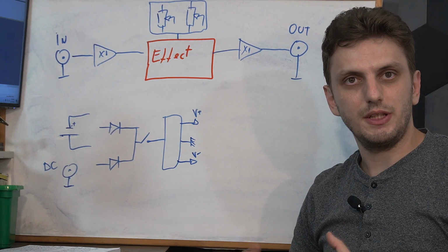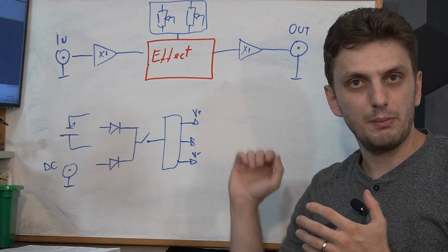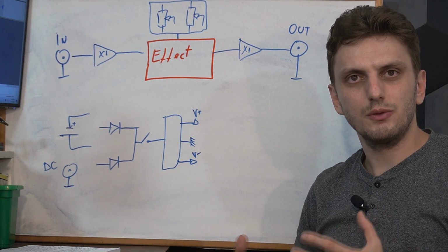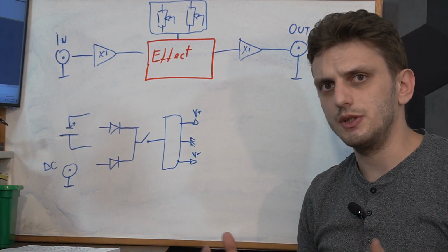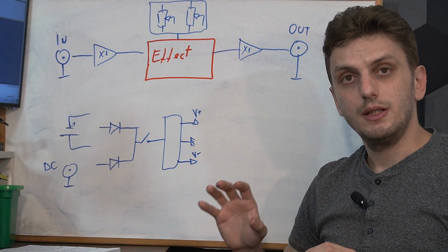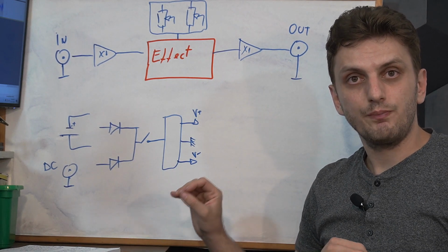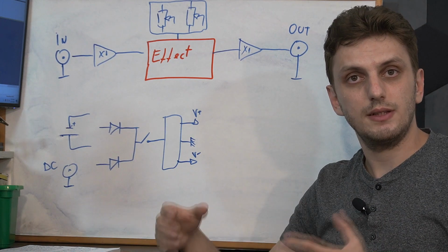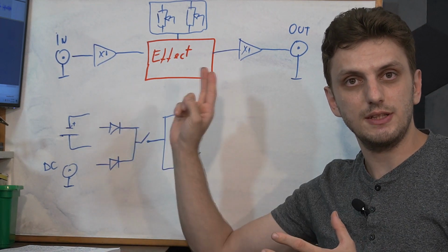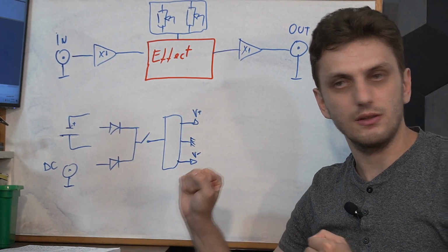So when you will be activating or deactivating the bypass circuitry, usually there will be some sort of interruption heard in the sound. And that's not something you want. So what I want to do is have my pedal switch and use that to run some sort of electronic switch that creates a smooth transition between the affected signal and the bypass signal.